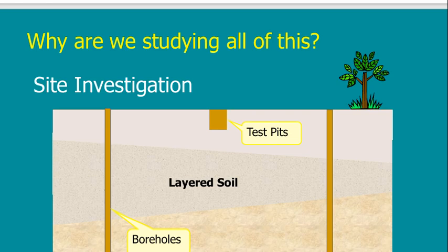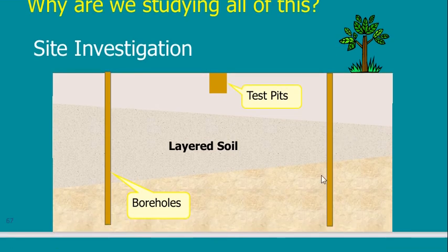In site investigation, I drill boreholes. Test pits are not important for geology, but they are important just for geotechnical engineering. But boreholes, especially deep boreholes, go far below the surface of the earth. I will see different types of layer.